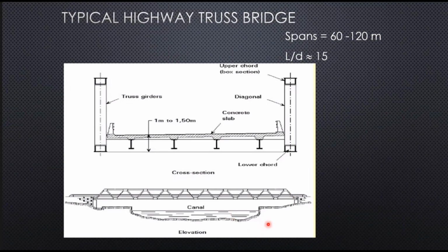You will not find many truss bridges on highways. It is basically because, in the case of a train bridge, the spacing of the trusses is very close, so when there is a load, better load transfer takes place in the trusses. But suppose you have a deck of 15 meters and a truss in between, the efficiency of the truss is not realized.